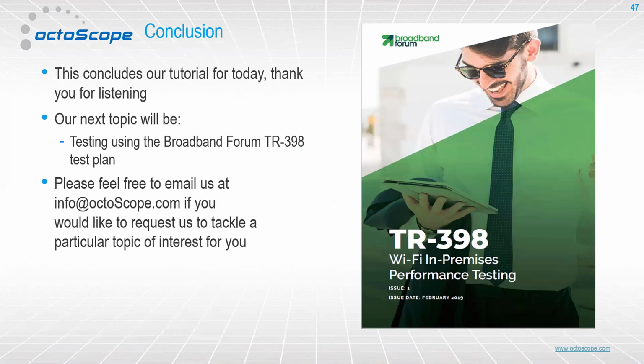Again, what we tried to show today was to explain the concept of a link budget in the concept of our test bed, and how we can create complicated topologies like meshes and roam devices through them simply by manipulating the path loss between the devices. So that's it for the day.